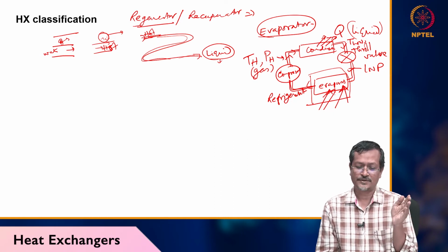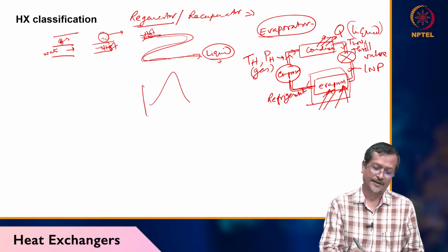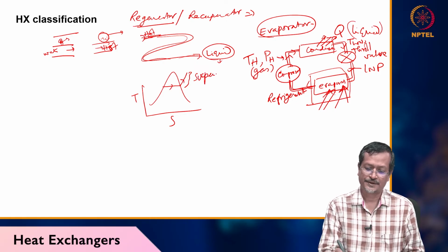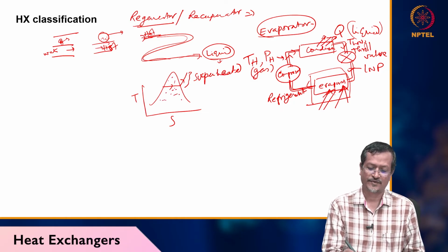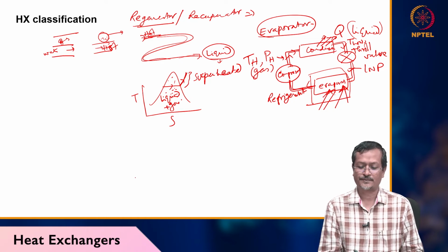In a boiler system you have a superheated boiler you are creating. Superheated, you can remember, I already told you the TS diagram. You are increasing temperature, you are increasing temperature further. So this area is the superheated area. Okay, inside this envelope it will be liquid plus gas. One process will be happening, but outside the envelope this area will be superheated, meaning completely gas.